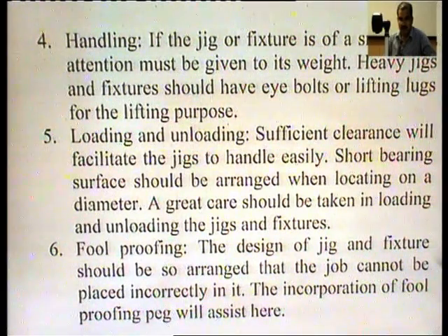Then loading and unloading. Again, sufficient clearance will facilitate the jigs to handle easily. Short bearing surface should be arranged when locating on a diameter. A great care should be taken in loading and unloading the jigs and fixtures.